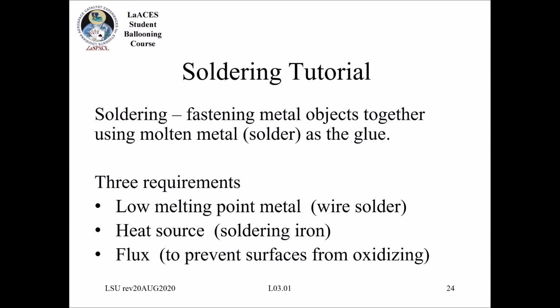And get the one that you are expecting it to be. Also, make sure that your footprint, if you do start doing layout, matches the part that you're ordering. It's very important. So we're going to be doing a soldering tutorial.